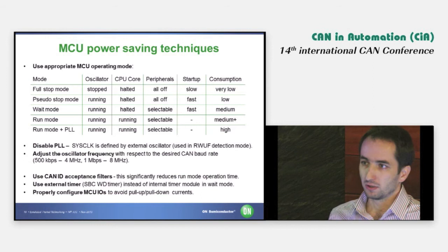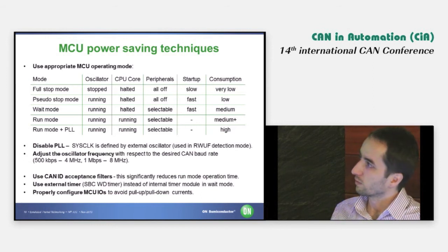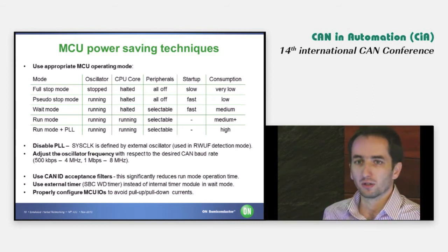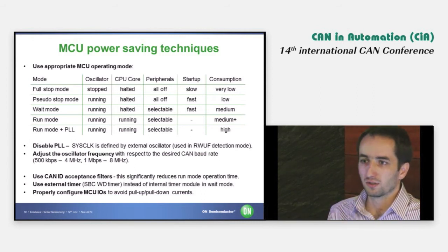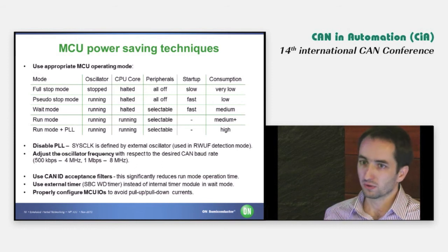Actually it writes an interrupt to the microcontroller, and the microcontroller switches from pseudo stop mode to the wait mode, where it enables CAN communication, and at the same time it switches the physical layer transceiver from the low power standby mode to the receive-only mode, where it can detect the communication and provide the data from the bus to the microcontroller. So the transition is very fast.